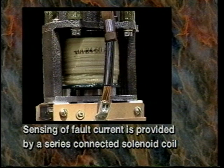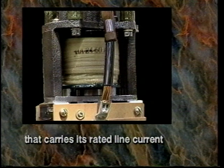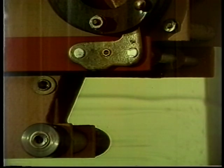Sensing of fault current is provided by a series-connected solenoid coil that carries its rated line current. When a fault occurs, tripping is initiated by a solenoid plunger. The plunger, normally held at rest by the closing springs, is pulled into the coil and causes over-toggling of trip springs in the operating mechanism that opens the recloser contacts.